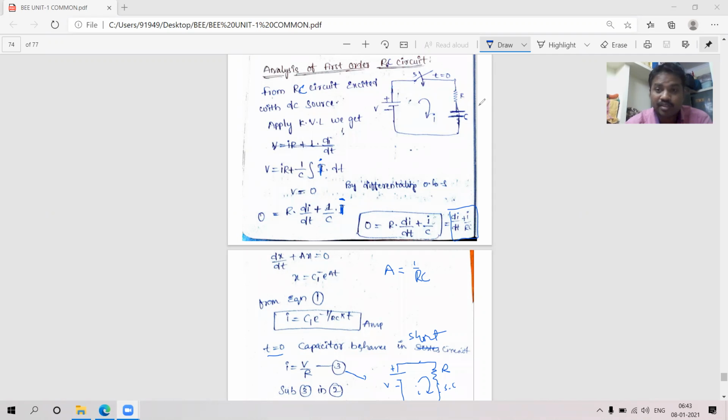And we know that at initial conditions and final conditions, the resistor will be the resistor itself, whereas coming to the capacitor, its initial condition depends upon the past history. The capacitor is a storage element, no? So it depends upon past history, so at the initial condition it is a short circuit. And at the final condition, when t approaches infinity, it becomes an open circuit.